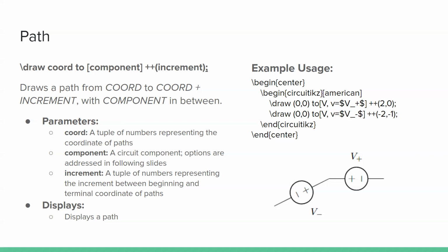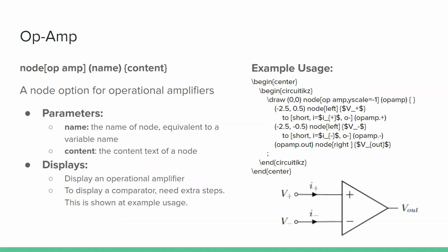Okay, so the reason why relative positioning is useful is because we have to deal with op-amps, which, as you see, is this little cute node here, but it's very difficult to find the exact points along which V out, V plus and V minus are located. At this kind of stage, to get the coordinate of these points, we can define nodes at these coordinates. And very gladly, we have the syntax to do just that.